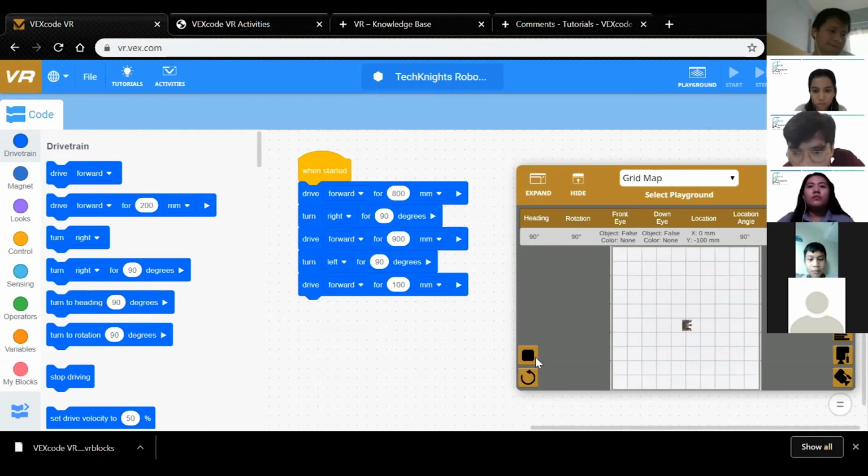And moving forward, 4 grid blocks, 800 millimeter travel, turning 90 degrees, and this time 900 millimeter, and then forward. Bam! We made it. So our goal area is 0 and 0 for our X and Y coordinates. We're now in the origin. We're in the middle of our box. So I was able now to teach you how to use basic drivetrain tools.